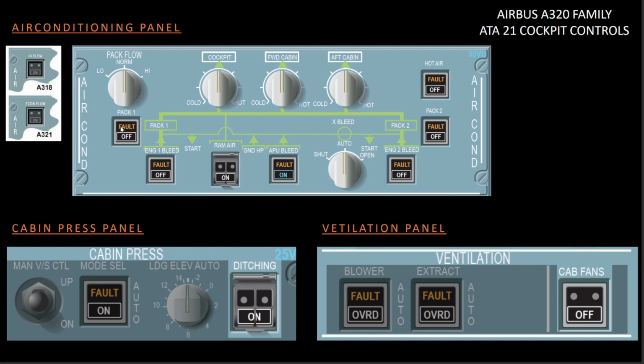In case there's a position disagreement between the flow control valve position and the cockpit selected switch, you will get this fault light.